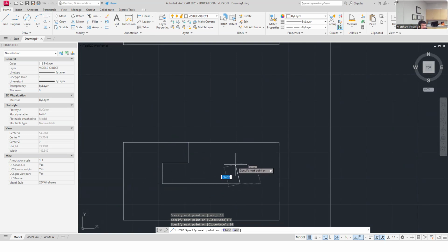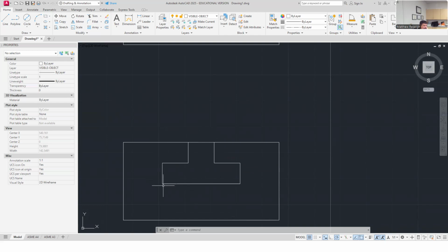And I could have drawn this in as a mirror image too, like we've done on some other things, but I'm just going to draw it all as one. What I had to figure is that 10-inch long line and then back up to here. So essentially I went over 5, drew down 8. I went over 10 because this total thing is 15 and I already had gone over 5. So I needed to go 5, 10 more over. And then back 30, up 8, over 10, up 8. I have my T slot.